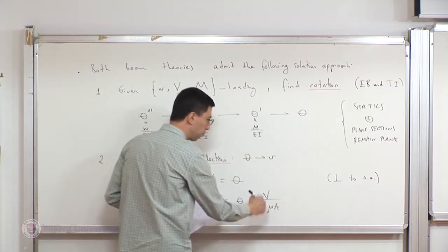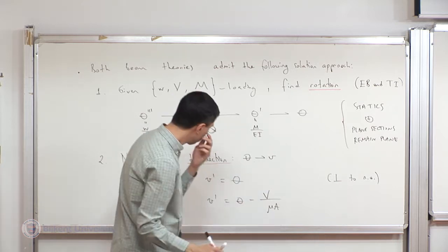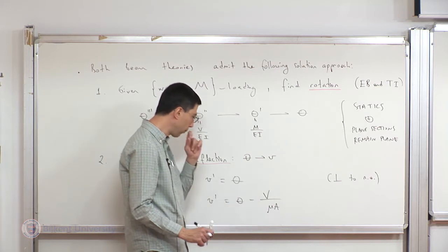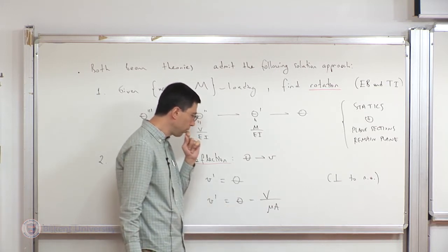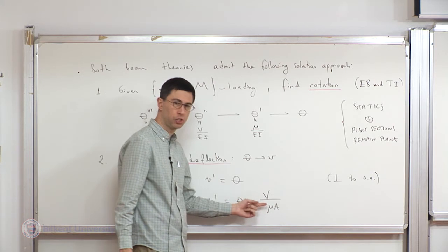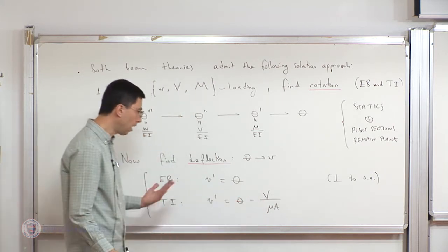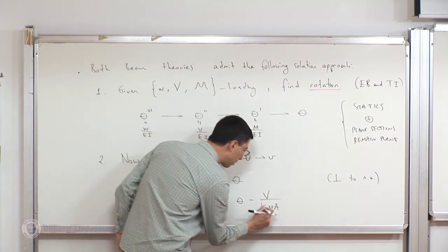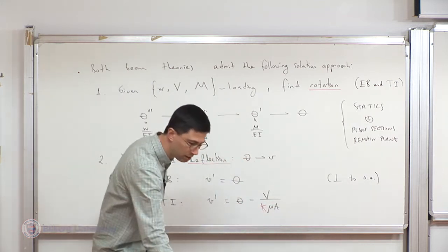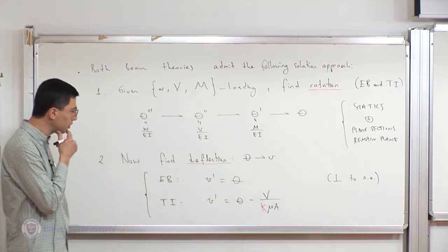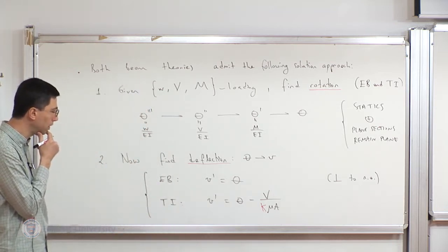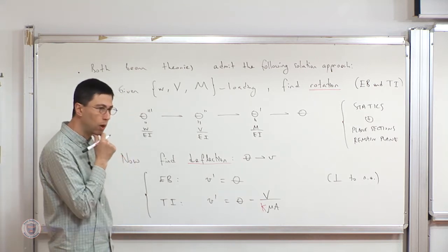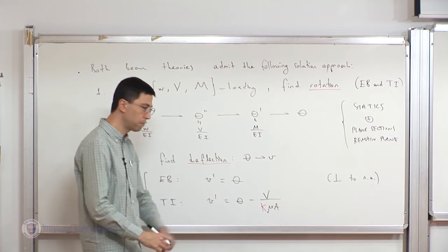Now, if we assume a constant shear stress, this is the result that we got. But then we also argue that, well, in reality, the transverse shear stress distribution is not a constant. I know that from the exact solution. So why don't I put here some constant that will account for the fact that it's not a constant, perhaps by adjusting this value k, which we call the shear correction factor. Perhaps we can adjust the quality of the solution that we get from the Timoshenko beam theory.